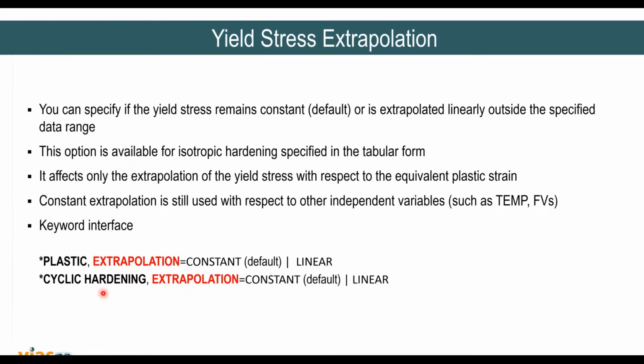Now coming up to the yield stress extrapolation. As you must be doing the elastoplastic material in your analysis, you must be aware that whatever elastoplastic material point you define, specifically *Plastic, basically assumes the plasticity constant at the end of the data point that you defined.